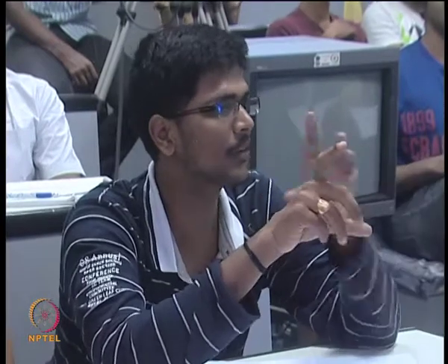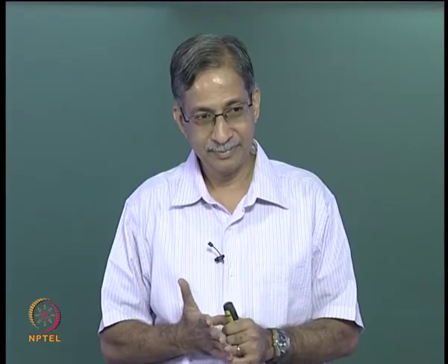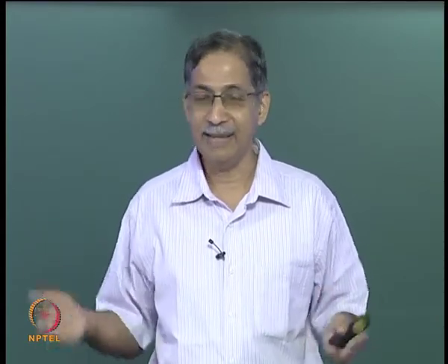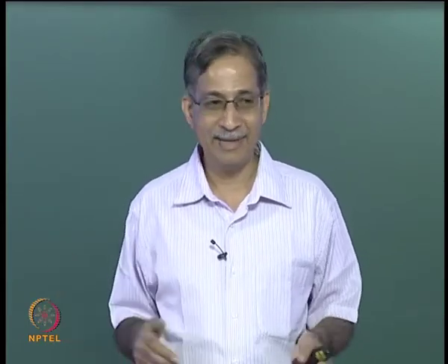So the member must be in tension, right? Tension or compression? Still in tension. Then if you take an inclined member, can you have a horizontal reaction? You can have a horizontal reaction. You understand? So there is always an answer to any question. It should make sense. Of course, one answer is the horizontal reaction is 0, but you know that is not going to happen because it is an over-rigid system, it is statically indeterminate, there have to be internal forces, there have to be support reactions, but the reactions will cancel out. Is it clear? Good question.